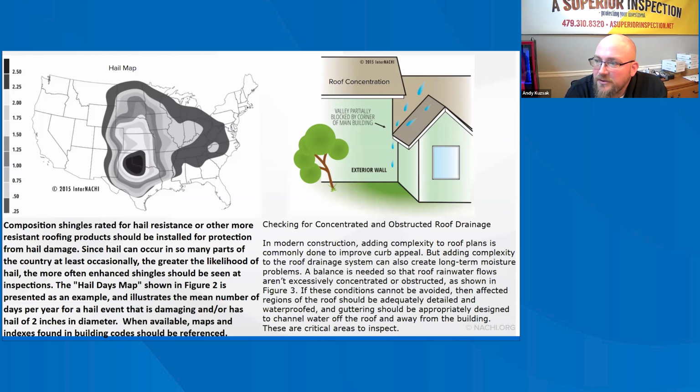Check the roof sheathing. The roof covering is only as strong as the substrate to which it is attached. Roof sheathing in high wind areas should be attached with minimum 8D deformed shank nails or 8D common nails, spaced 6 inches on center at all framing members. Full round head or D head nails should be specified and should not be overdriven into or through the sheathing, as this severely weakens the connection.